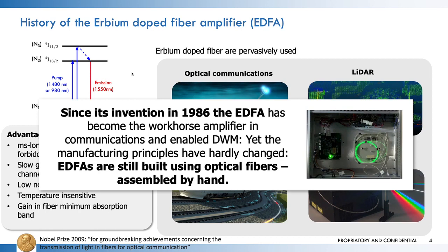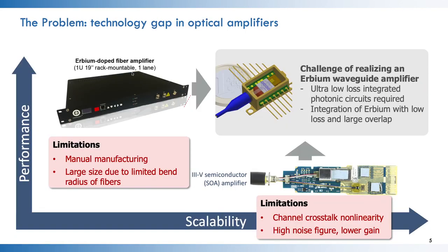Even a product like the small form factor pluggable EDFA available nowadays has a bending radius of about a centimeter, and it's also assembled by hand. So there is a problem to really scale up the number of channels for different multiplexing applications.